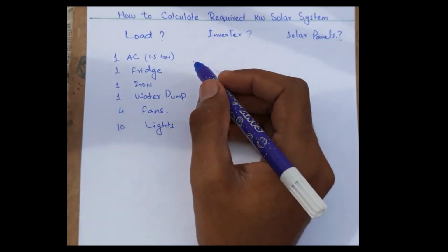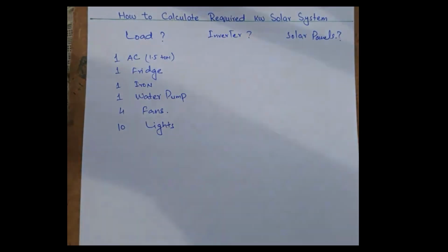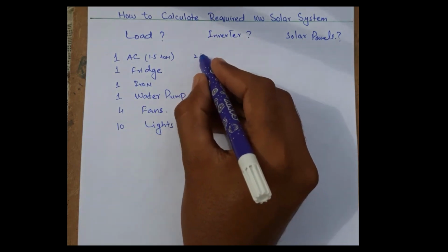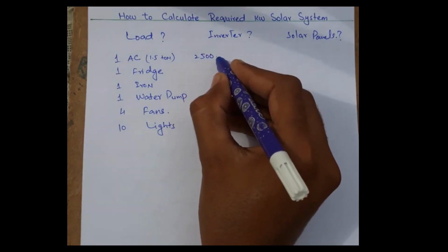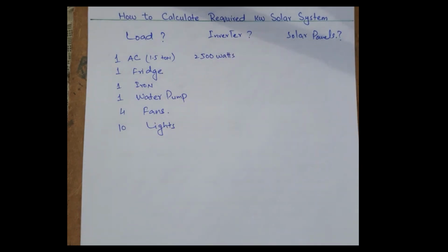Therefore, your home will need an inverter that can handle this load. A 3.6 kW inverter would be enough to manage this load easily. In the market, you will typically find inverters in the range of 3.6 kW, 4 kW, and even 4.2 kW.